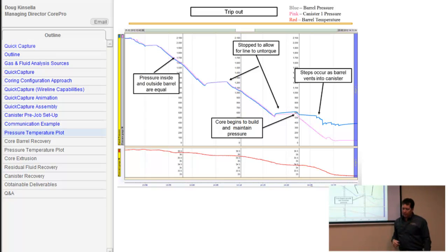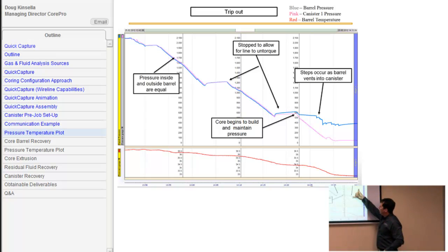The longer vertical lines, that's what we believe to be a sign of whether we're pushing all fluid, all gas, or a mixture. If you were to let the air out of your tire, it takes quite a while to take any volume of air out. If you're pushing liquid out, you can advance a small amount of liquid and it decreases the pressure incredibly quickly. So a long line like this would suggest we're pushing a lot of gas out. A very short line like this would show us that we're probably pushing with the gas, we're forcing a bunch of volume of liquid out as well. So it's the duration that the pressure relief valve is staying open.